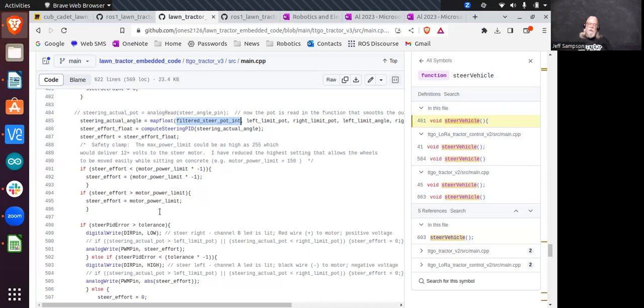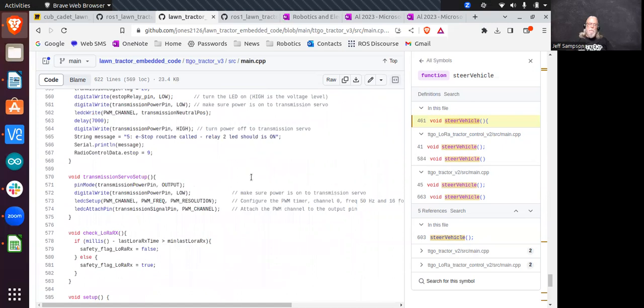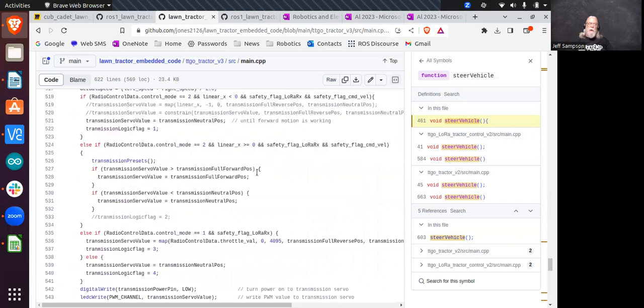Right now you've got something in your code that says, I just received a command velocity with an angle, and you're taking that angle and feeding it into the PID and slamming it over to that point. Instead, take the incoming value, create a new variable called target angle, and slowly increment that each time through your loop, and that'll slow down the steering. So it's not trying to go from one point all the way to the other point at full power.